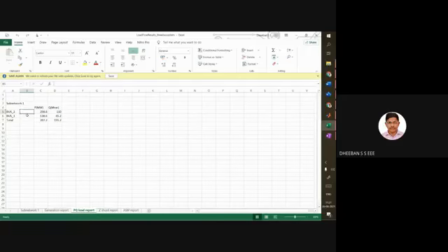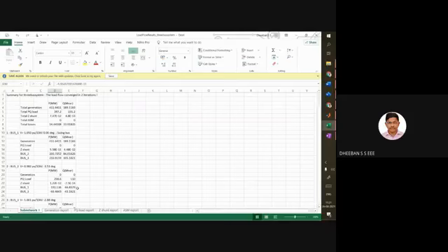So the number of loads connected to the particular bus, we can get it out. It is around 258 megawatt. The total power also gets calculated, and finally, you can get the Z shunt. With this Z shunt, you can also see the amount of power flowing, and each and everything can be gotten out. So this is with respect to your 3-bus system.